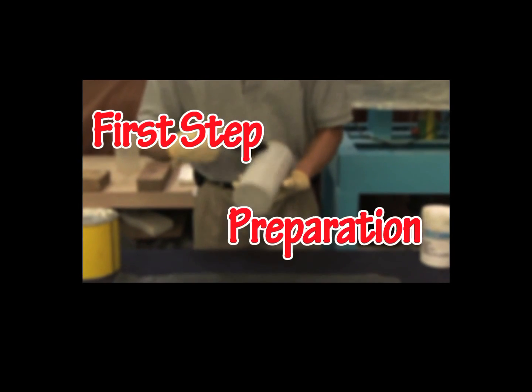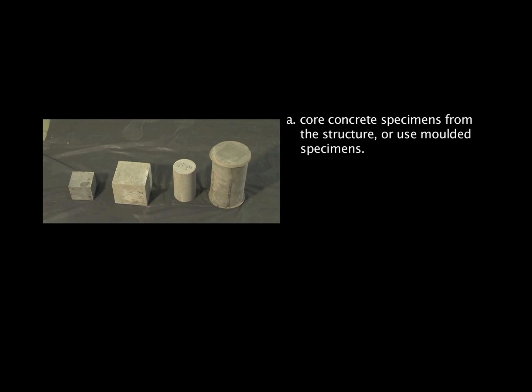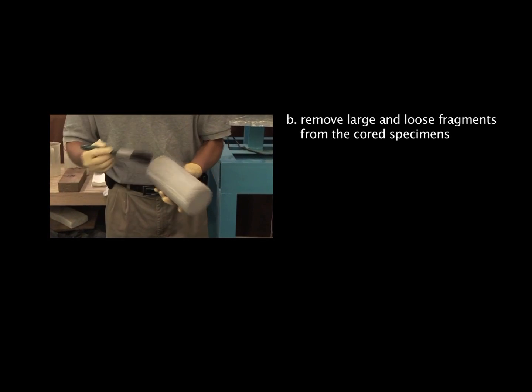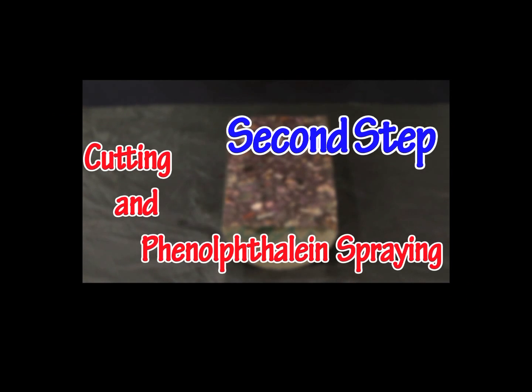Watch each step carefully. The first step is preparation. A. Core concrete specimens from the structure, or use moulded specimens. B. Remove large and loose fragments from the cored specimens. The second step is cutting and phenolphthalein spraying.